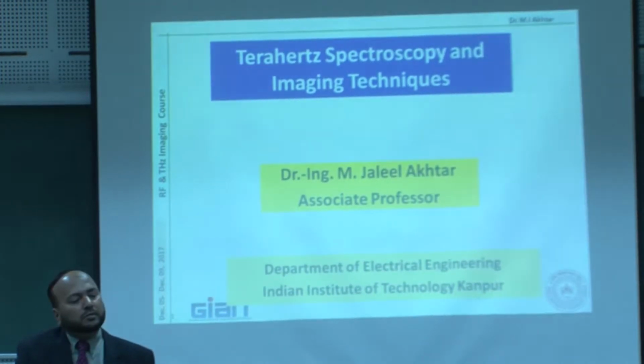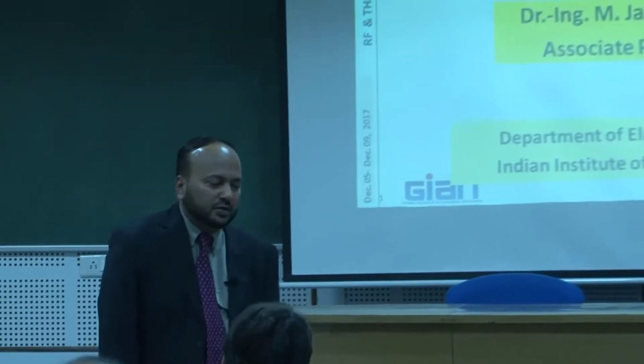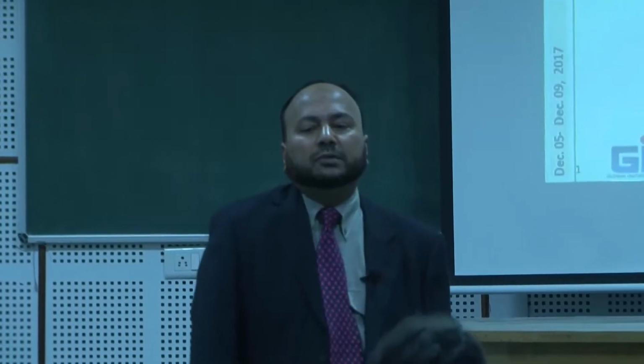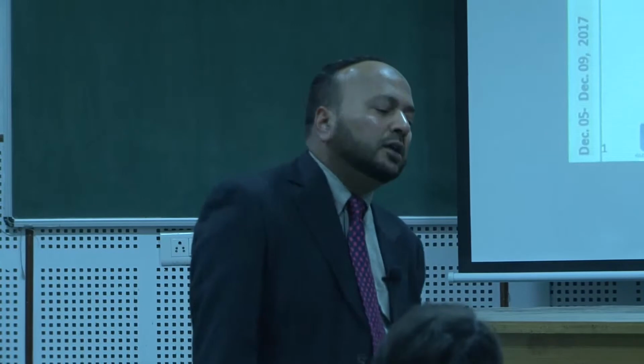Of course, they mostly are what we call far field imaging, and as Professor Umar had mentioned yesterday also probably, far field imaging means you don't have any physical connection, and if you have a far field, you have plane wave approximation. So analysis becomes simple. Of course, we also have what we call sometimes near field imaging, which we will discuss today later on. So there are always pros and cons of both types of imaging. Far field is contactless, while near field could be contacting, but there are also advantages. For example, if you have far field information, then you can imagine the signal will be weak, so from that point of view, it will be difficult